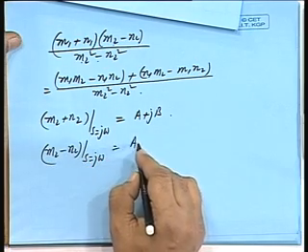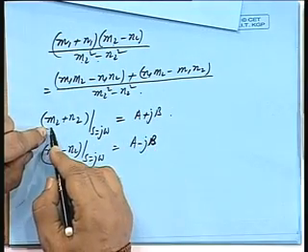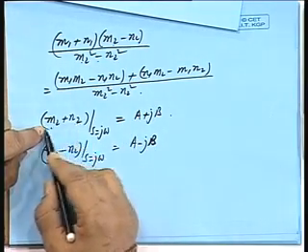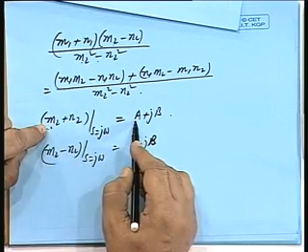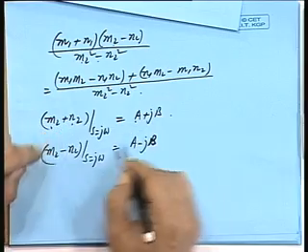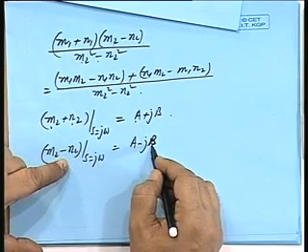It will be a minus jb, is it not? Even part m2 plus n2, so even part will give you real part, odd part will give you imaginary part, and it is the odd part whose sign is changed, so it is going to be minus jb.